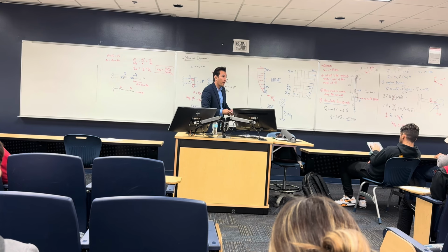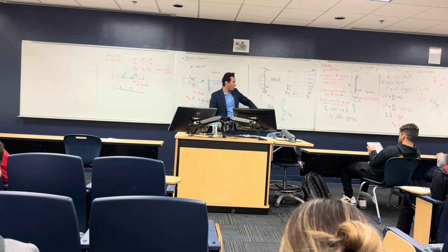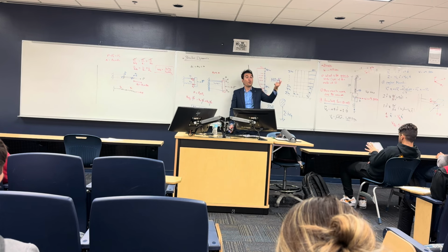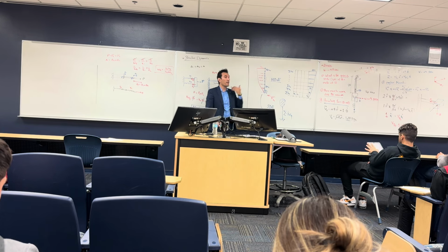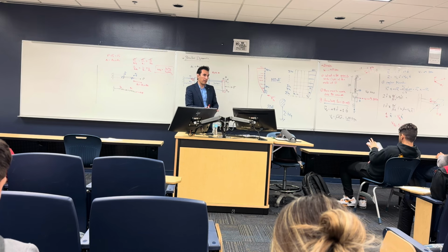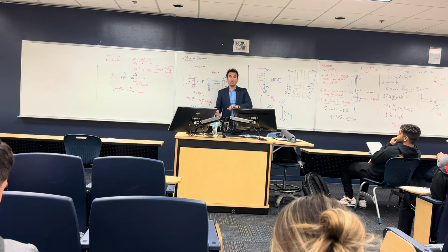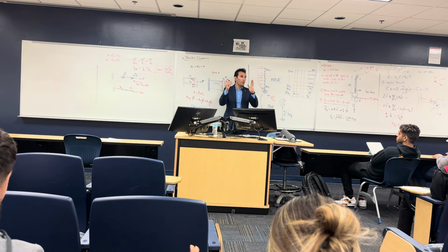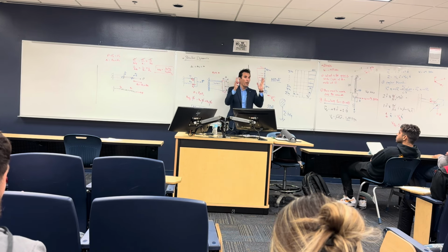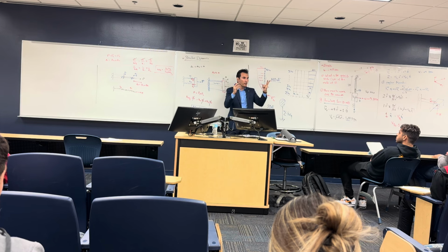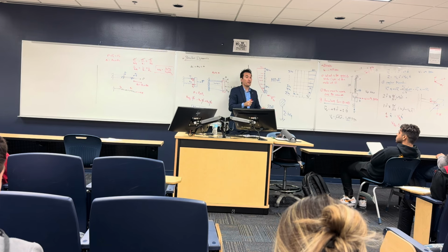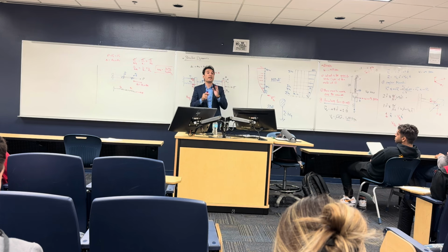So when an earthquake hits a structure, this structure is going to resist this earthquake with the stiffness of the columns. So the second thing that I need to think about is something called damping. What is damping? When an earthquake hits a structure, is the structure going to move forever? No. At some point it's going to stay still. So what makes the structure still? Two things are resisting, or three things: the mass, the stiffness, and there is a third component called damping.